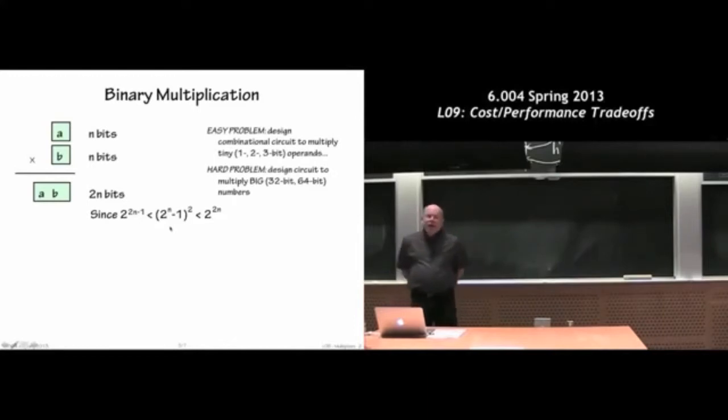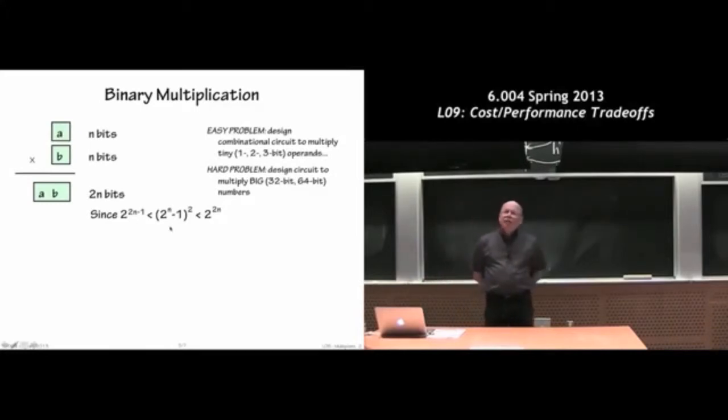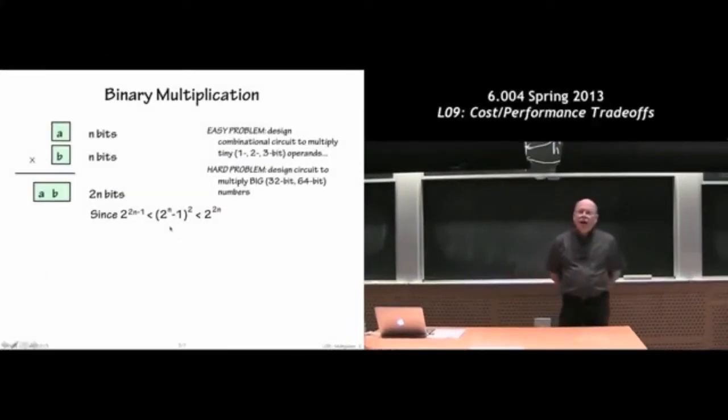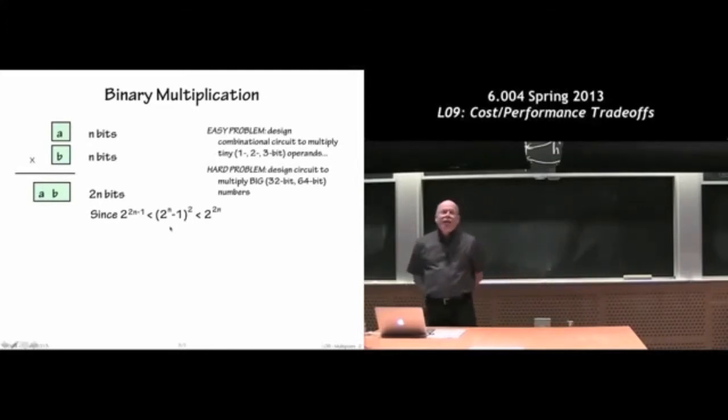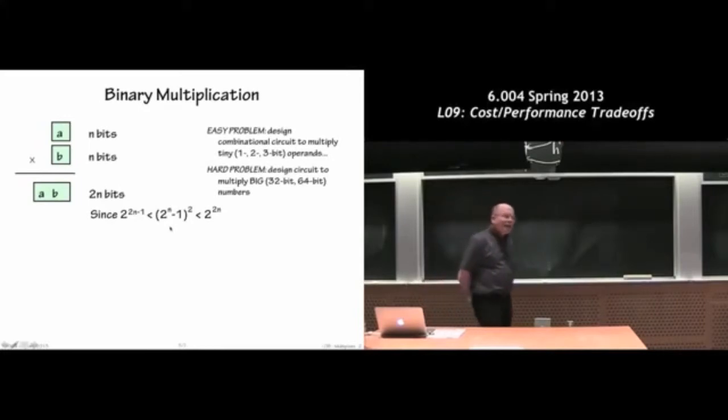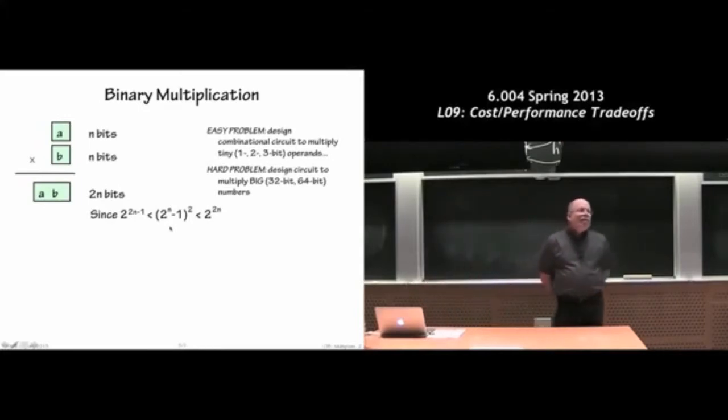It turns out that for small multipliers, like even a 1-by-1 multiplier, the hardware isn't too bad. But puzzling a little over how to build a 32-bit by 32-bit multiplier, you quickly realize that's a lot of hardware. There are lots of partial products to create and lots of adders needed to add them together, and your fingers are getting shorter as you type them in.